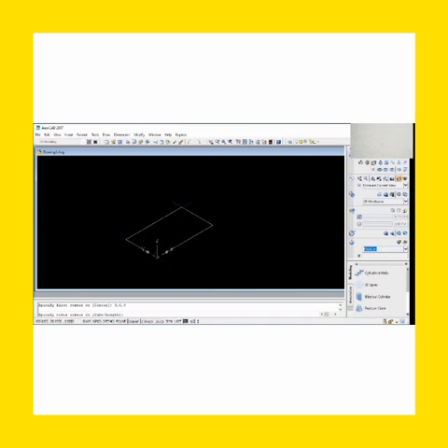Now you have the options of keyboard length. So you choose the option of length. That will be L, enter. And now we're choosing a length of 100, so type 100, enter. And then the breadth is 64, I mean, that's the width. So 64 is already there, so you press enter. While the height is 50, so you type 50 and then enter.